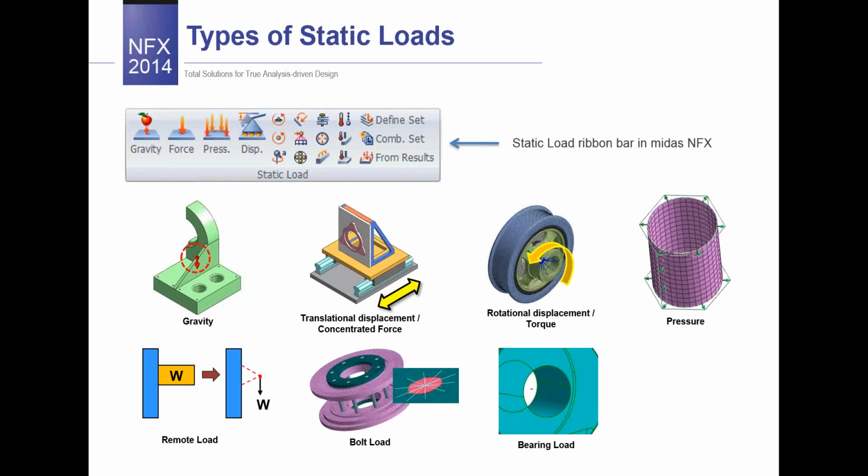Now let's take a look at the types of static loads. Similar to boundary conditions, loads can be applied directly to geometry or mesh, which means nodes and elements. So we can apply many types of loads like forces, moments, pressures, translational and rotational displacement, centrifugal forces, follower forces, etc. And all of the available types of loads have been grouped in the ribbon bar.